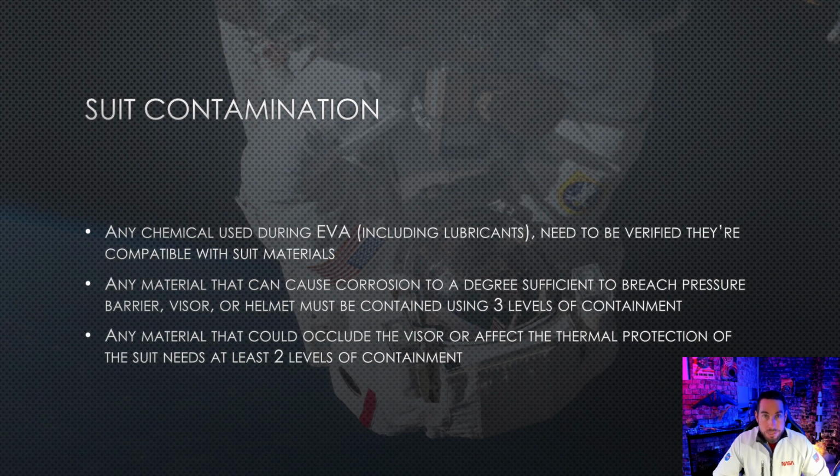So any chemical that's used during the EVA, and this includes something as simple as a lubricant, there's extensive testing that has to be done to make sure that it's compatible with suit materials. So you can't have anything that's going to weaken the seals, that's going to stain it and degrade the thermal distribution of the suit. Everything has to be proven to be compatible before it can be introduced into the EVA environment.